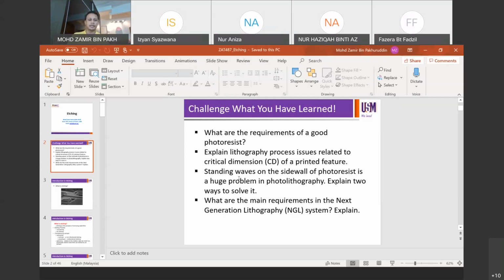Right, so let's move on to low defect density. Yes, low defect density, good. You don't want to have defects from your resist testing as well. And a good addition: you want the resist to adhere to the HMDS and the wafer, and you don't want to have pattern collapse in the process. So at least you've got 5 already.